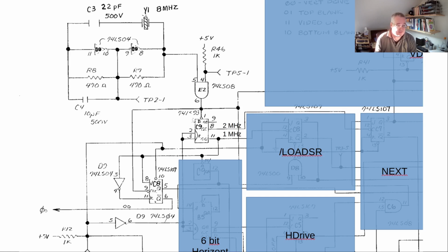And there is a JK flip-flop. JK flip-flop, if you don't know them, look them up. They are a very basic form of logic gates. And the main thing is if J is set, when the clock goes down, the output Q is going up. When K is set, when the clock goes down, Q is going down. So it's in a way a clocked RS flip-flop.